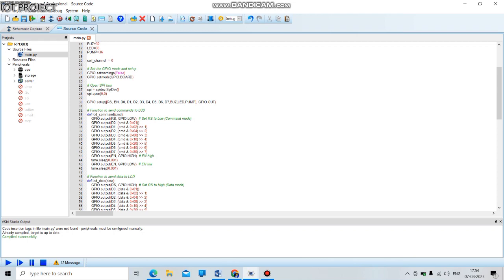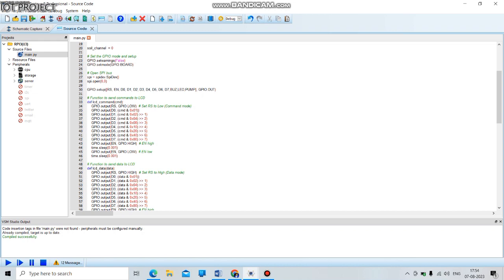So we have to shift the eighth bit to the last position, and for that we have to shift it seven times, so we write 7 at this position. Similarly, this function works: the GPIO output pin takes firstly the pin number and the pin status. So we have to set this pin status in this form.